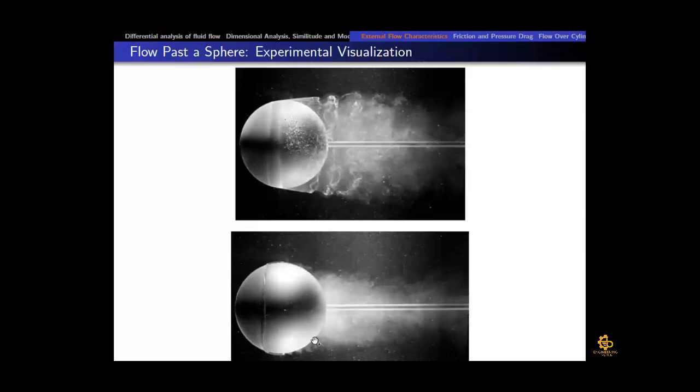So on one side we have a vacuum due to flow separation, and on the other side we have flow attachment due to the turbulent boundary layer. So if the upper side is shiny and the lower side is rough, the ball would always travel towards the shiny side, because the shiny side has flow separation and the rough side has the boundary layer attached due to turbulence. So that is the case of reverse swing in a cricket ball.